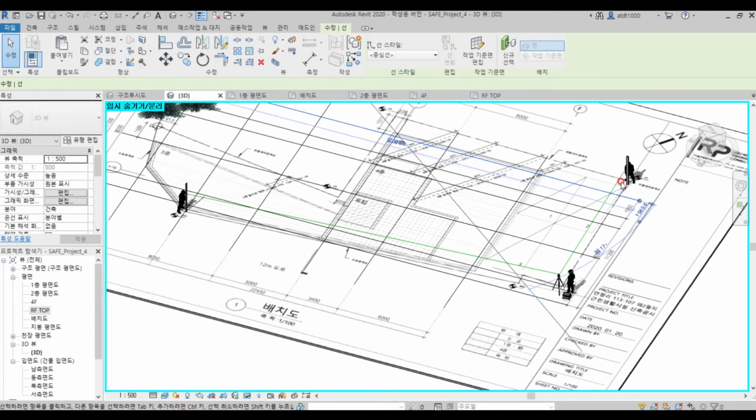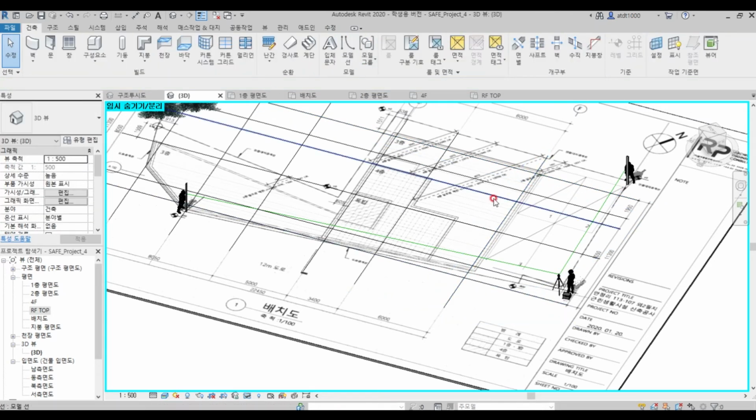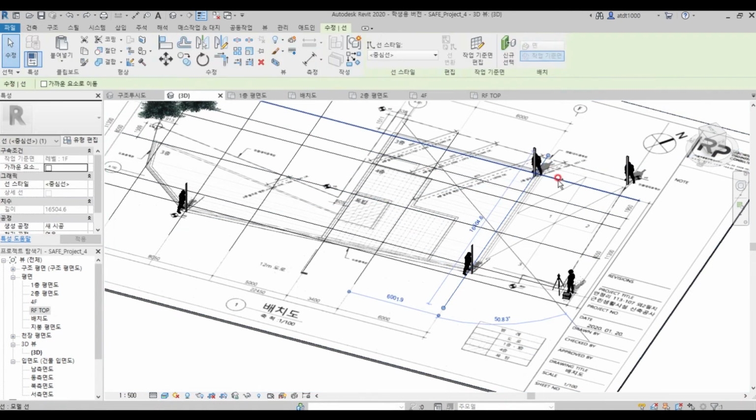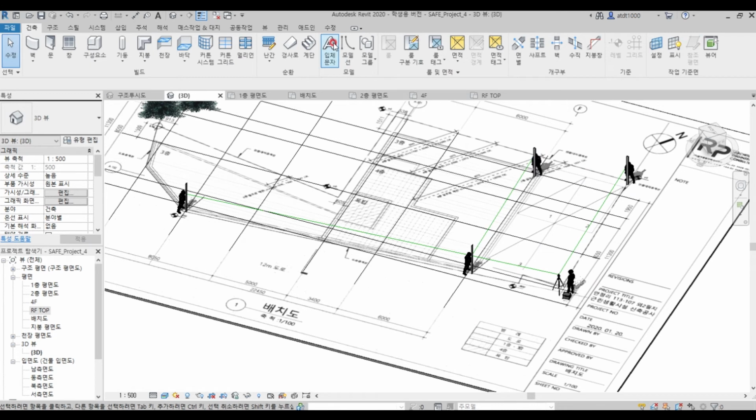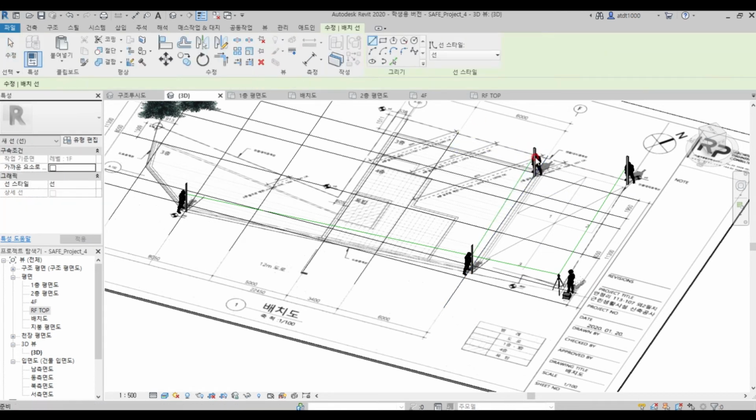Then a reference point of the building must be set up. For example, if I define 2 intersections of the grid as reference points, the location of the intersection of each grid and the boundary of the site must be checked. Surveying should be processed again for accurate measures, and a precise reference point can be obtained with the measured distance.